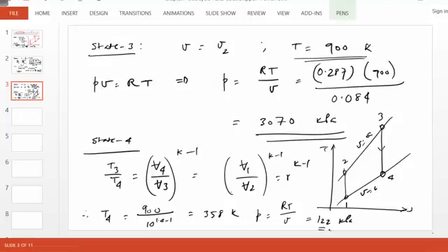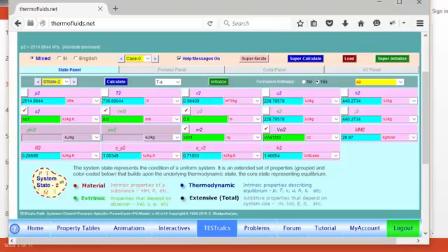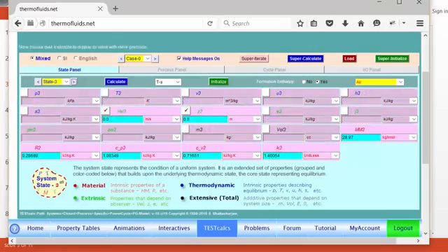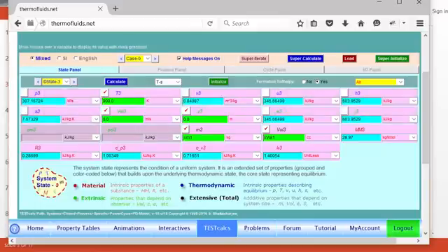Immediately some gas escapes because of the pressure difference. Well, let's go and verify them. State 2, we shouldn't proceed without verification. And state 3 is the highest temperature of the cycle, given to us as 900 Kelvin. And the specific volume, well, we can write down mass doesn't change and the volume doesn't change. Remember, the combustion happens very, very rapidly in a gasoline powered spark ignition engine. This way specific volume remains the same, or the volume and mass remain the same.